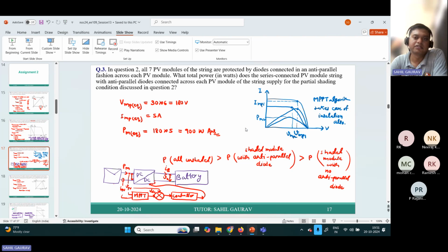No, no, it is not true. You are getting it the wrong way. You are not understanding. Whenever the power from the PV panel is maximum depends upon you, on what amount of power you want to extract from the PV. If you have set the voltage different from the maximum power point voltage across the PV, then it will give less or a different power. It is not true that you turn on the switch when the power is maximum.